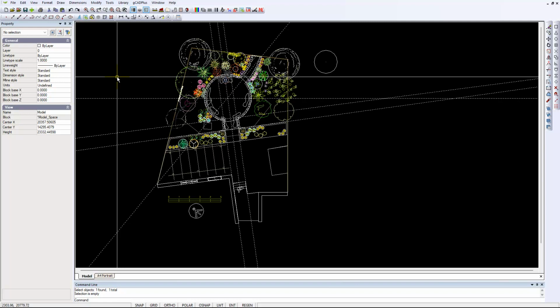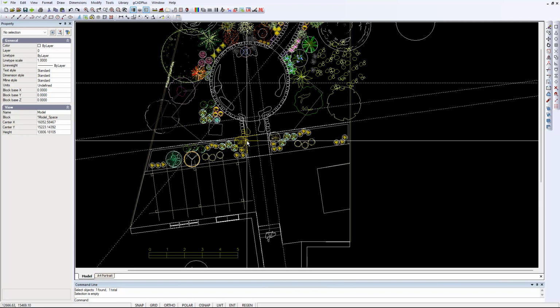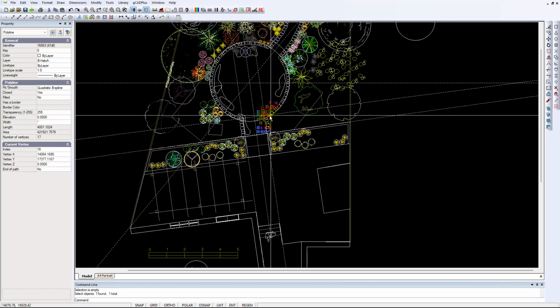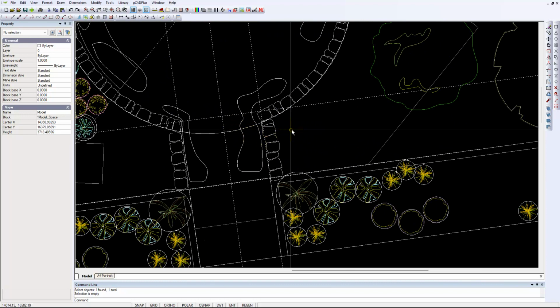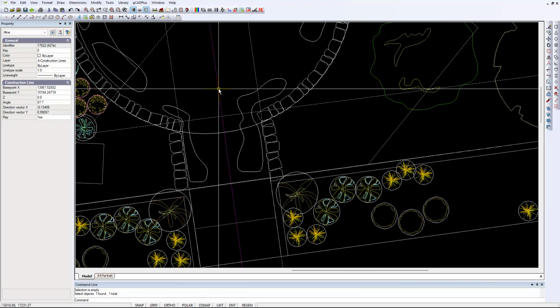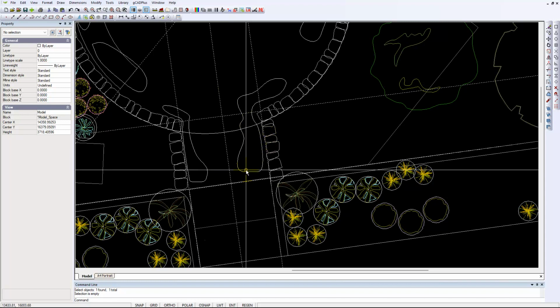So it's one way of just testing your drawing. If you find a drawing becoming unstable, there is a way around the problem. We haven't lost any base information here, but some of the subtle things like these poly lines were in fact hatched, but you can always go back and hatch again. So these construction lines and others all moved across very happily. So I hope you find that an interesting technique to fixing up a problem you might, we hope, rarely come across.